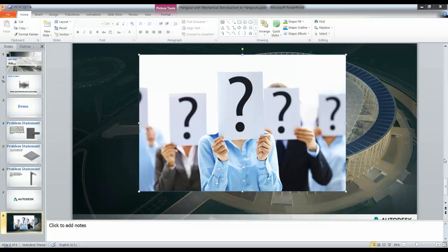So James, one of the more recent questions that came in was regarding the use of beam elements for the last example presented. How do you determine a 2 millimeter diameter? Why not simply use rigid elements? It's honestly a personal preference of mine. Rigid elements will function just fine, and it's easier to adjust by defining just the stiffness alone. I use the beam elements because I use them a lot for joint and remote loads.